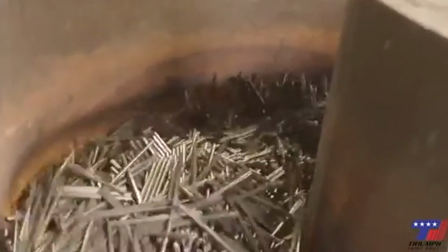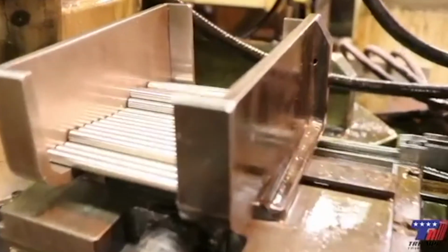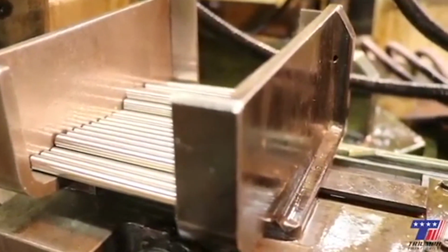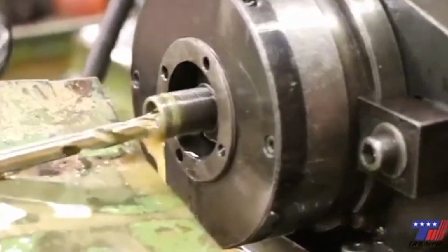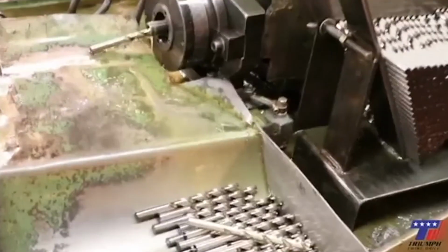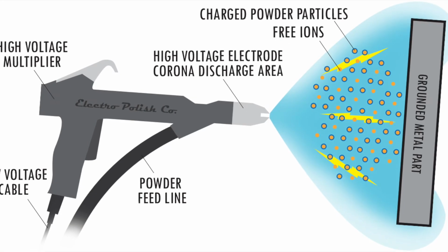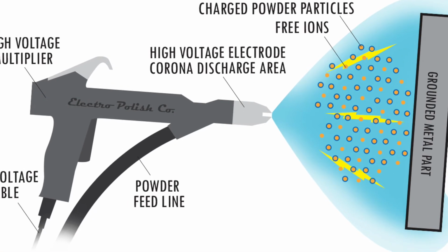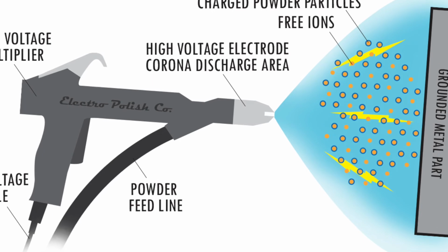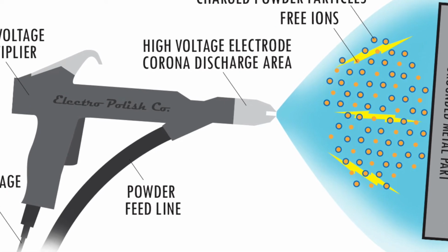The next step is grinding, polishing, and sharpening, which is cutting the flutes into the steel rod, preparing the surface for coating and sharpening the edge of the flutes. Coatings are important to protect the drill bits and increase the lifespan and the hardness. It can be done in various ways, such as painting.